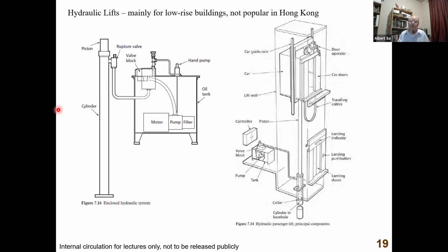for pumps, for compressors, for fans in the air conditioning systems, they usually rotate in one direction. So the first difference is unidirectional versus bidirectional. The second one, for pumps, fans, compressors, all these, what you're concerned with is the steady state movement, right? Steady state rotation. So you don't care how the motor accelerates or decelerates, right?